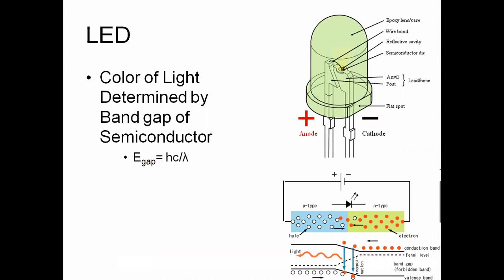Fermi level, you are also familiar with the Fermi level graph. So what is this graph? It shows when the electron, which is the majority carrier in the N type, enters into a P type, that means when it crosses the depletion layer. So what will happen? If you see the bottom line, there is a recombination of holes and electrons that takes place, isn't it? If you see the orange color electrons and white color holes, the recombination of electrons and holes takes place.